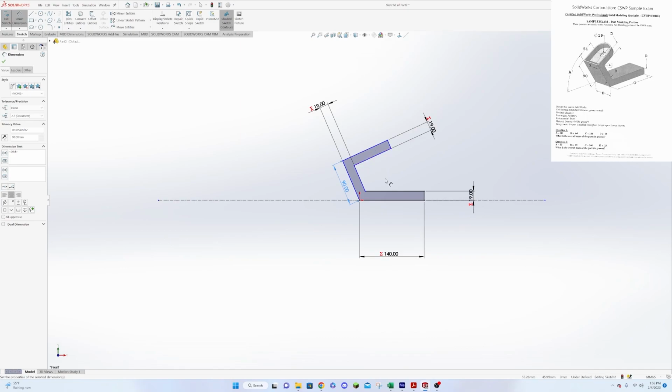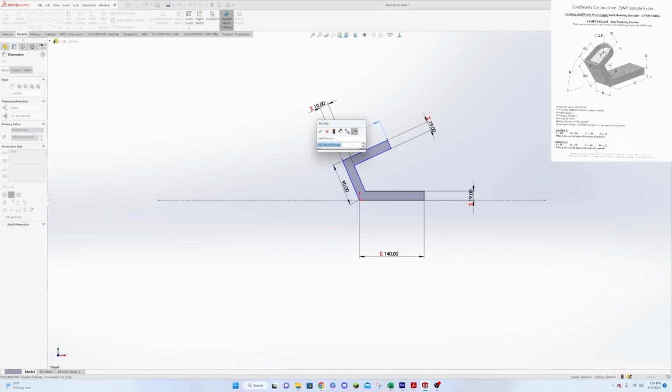And then we have this value up here, and this is where the first time that we use E as an option. So this line is going to be equal to 51, but then it's going to have the radius of the circle up at the top. And so what we can do, we know that radius is going to be half of B if we look at the drawing. So if we go here and click on this, and we drag this up once again, make sure that our line is parallel here. It's fighting me a little bit, but we got it.